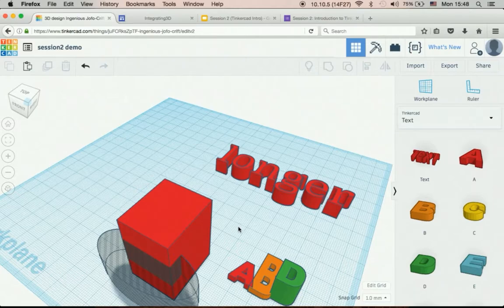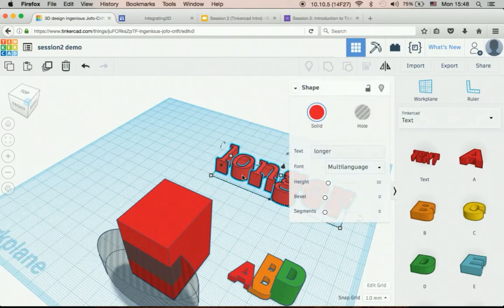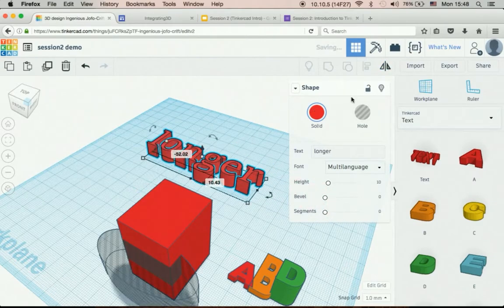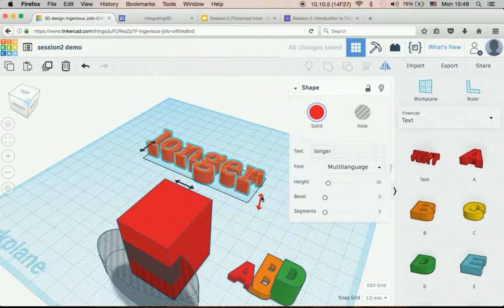A couple other things I want to show are some more of the tools up top. Right next to the alignment option, there is a flip option. If you click on a geometry and say flip, you get these 3 arrows, and it will flip things in that direction. So if I click here, it'll flip things in the X direction. So you can see that.